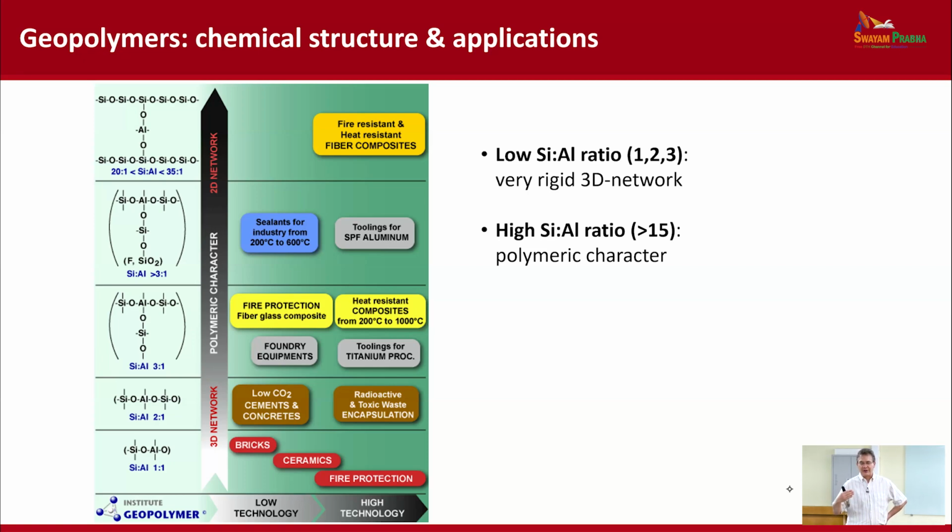And the advantage of having a fully inorganic system with respect to an organic binder is, of course, much higher thermal stability. So anything that has been made using polymers as a binder or as a matrix could be substituted with an inorganic binder. And if it is a geopolymer, it can withstand high temperatures. Of course, the component will have different properties, so not everything can be substituted.